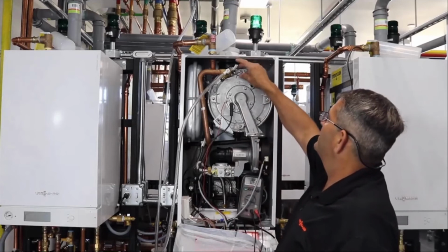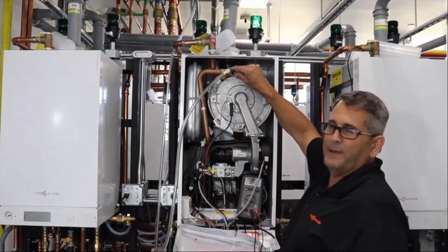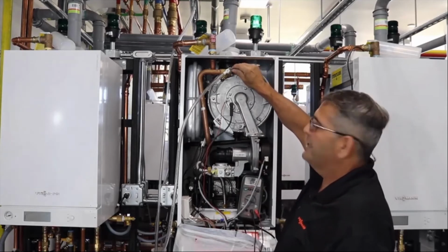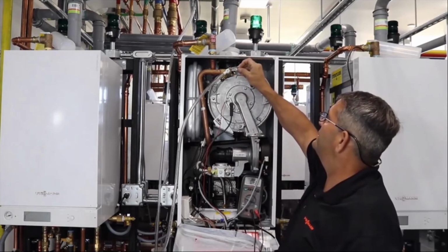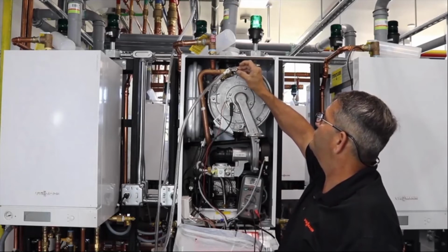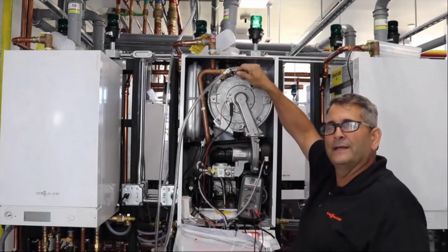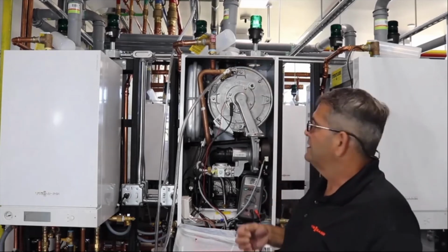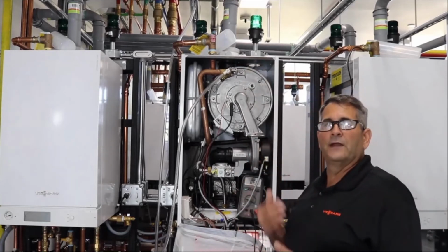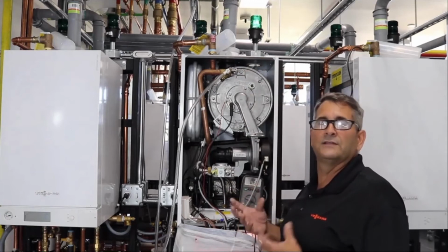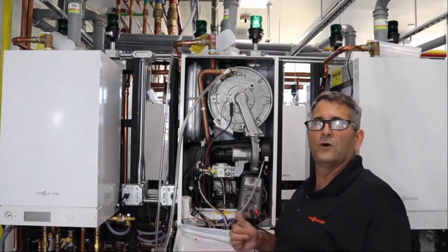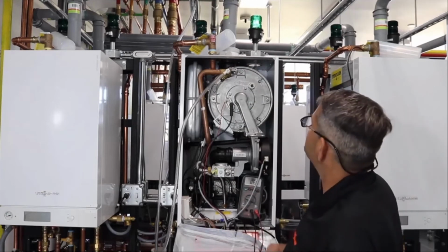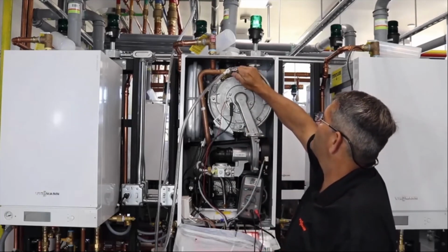So we did find out now that the sensor is bad. It works, it doesn't work, snap switch. What you're going to find if you do get there and you're off on an F2, the fan runs for about 10 minutes. So it's going to try to cool off the boiler itself, and then you'll find that the fan will shut off. But when you get there and the fan is running itself, you definitely know that it went off on high temperatures. So for this here, we're going to take off your 2 wires,